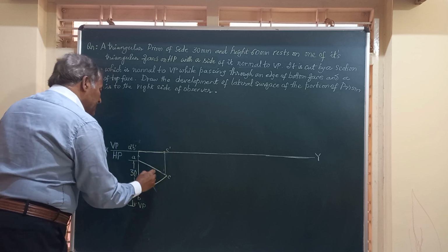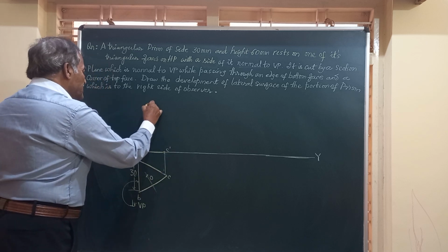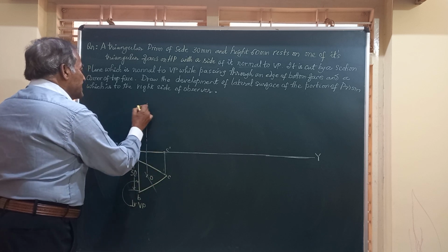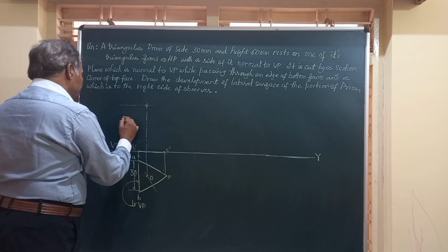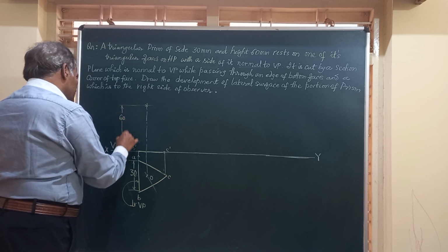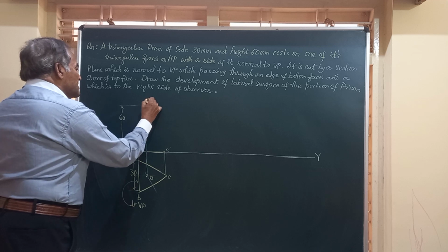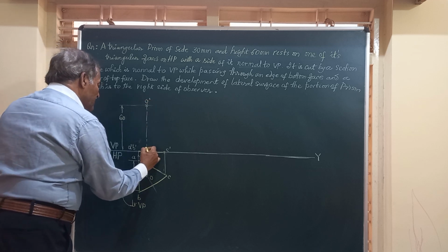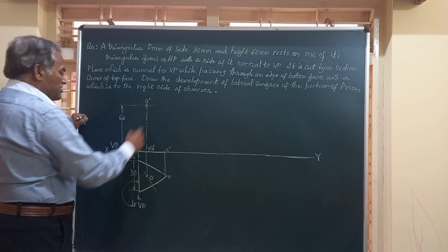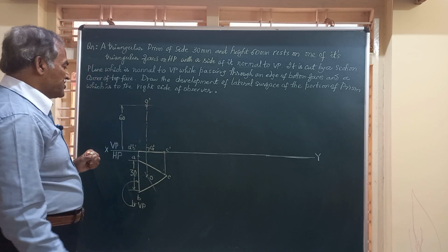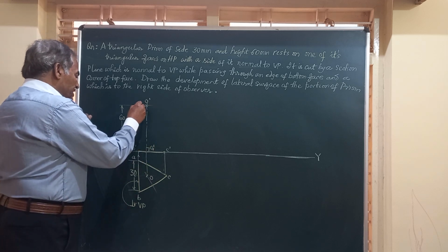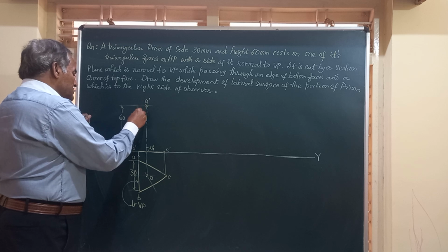We know the axis height. So from here, draw a vertical line, mark the height of 60 mm, that is the height of the prism, and obtain the center of the top face, that is O dash, and the bottom face is O1 dash. Remember, O1 dash is perpendicular to the HP. And now friends, obtain the top face by projecting this line further up.